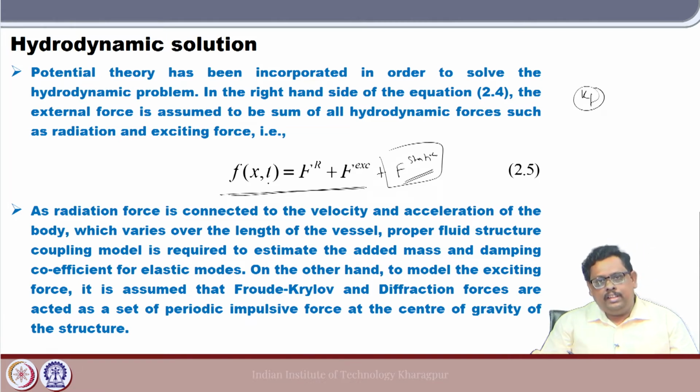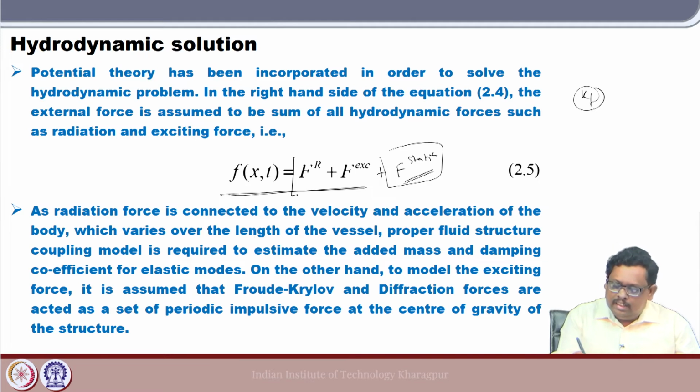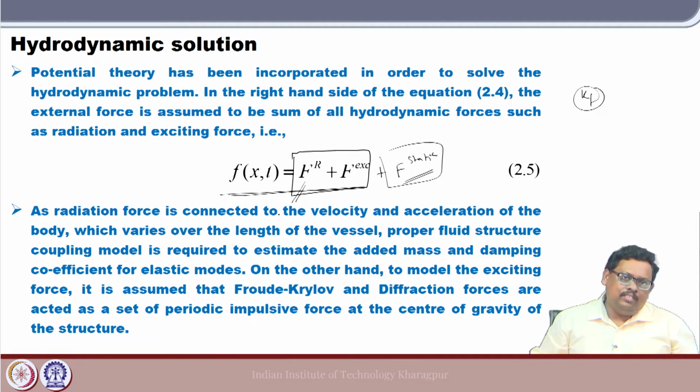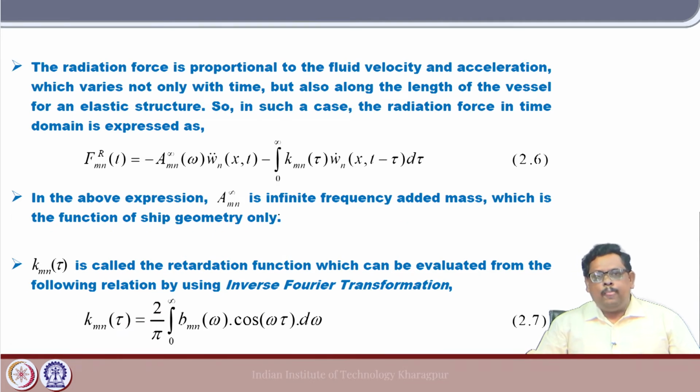Now, here the more important part is how I write this radiation force and the exciting force in a semi-analytic manner. For the radiation force, this is not that complicated. It is very well defined, in fact, we do not have to use much imagination to find out how I write that radiation component. You know very well that when you oscillate the body, you are oscillating the still water, and then you can oscillate in all 6 modes for the rigid body, right.